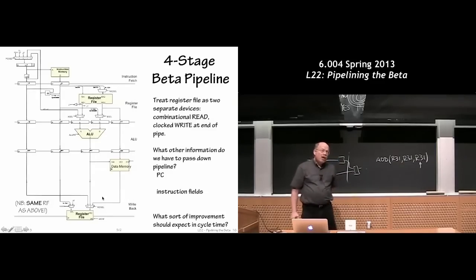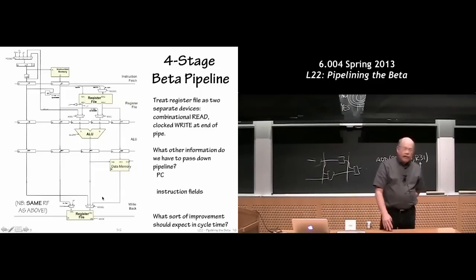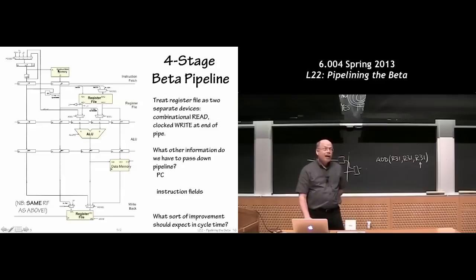Okay, so deep breath. We added that one pipeline stage up here, this one here, and then we had to deal with this backwards wire. Right, this idea that we're making a branch decision here and doing some computation that affected what we wanted to do in the earlier pipeline stage, and that caused us to add some hardware and do some annulment and deal with that. Okay, let's go ahead and continue our exploration about adding additional pipeline stages.